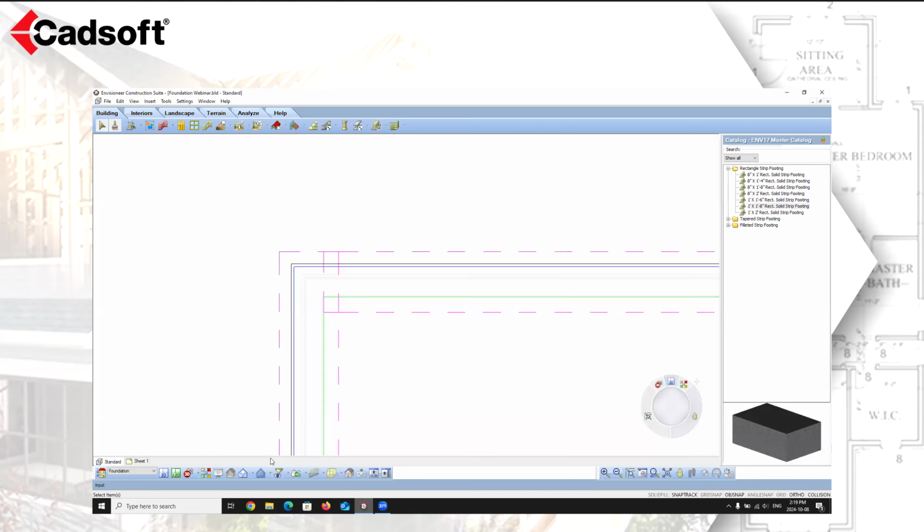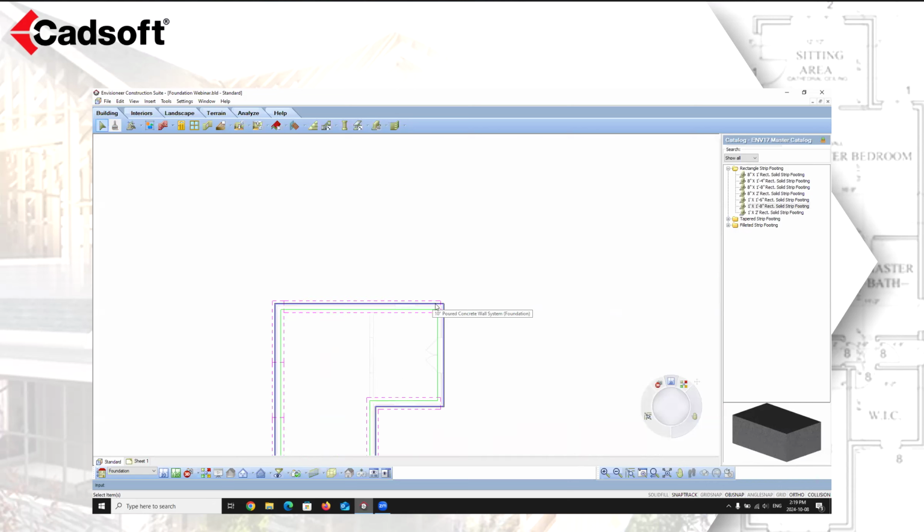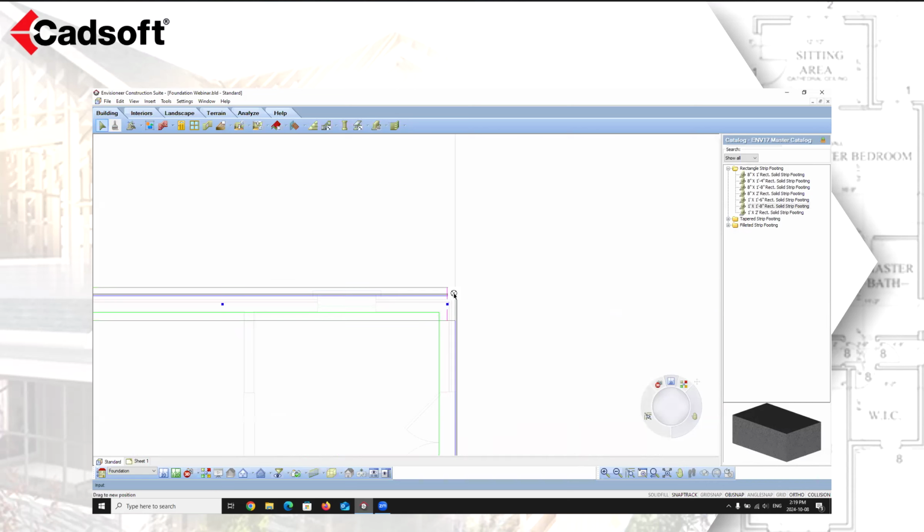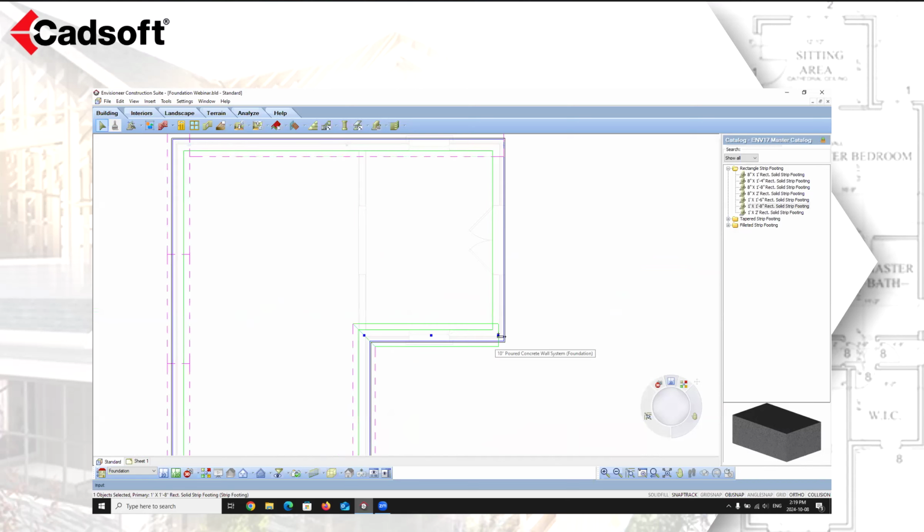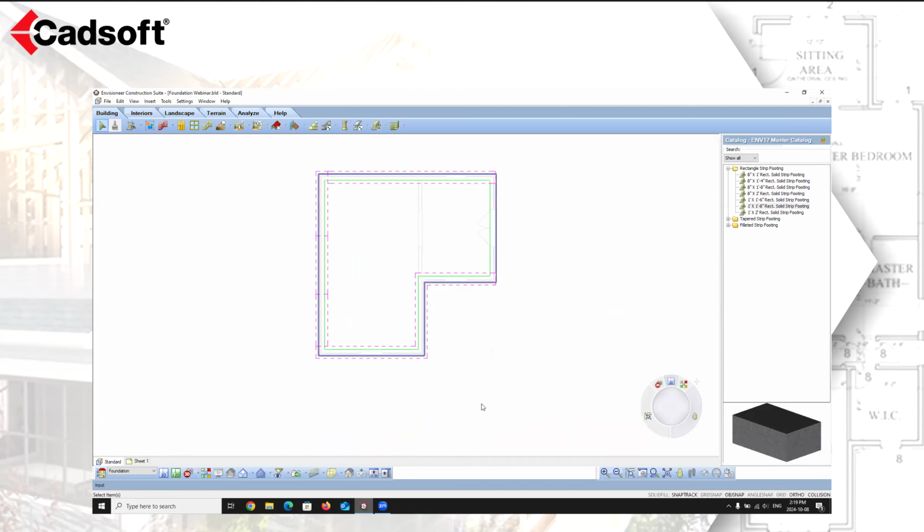So now we go back into our 2D plan view. We can again fine tune the placement of wherever our footings are going to sit. And we can go in, and we're now going to take a look at adding in our pad footings. So if you've added a column to your foundation, you can easily insert a pad footing underneath it. We're going to select the Insert Footings, Mono Footings Attached to Columns option.